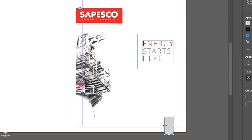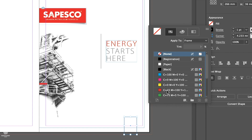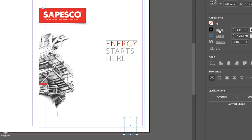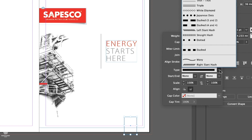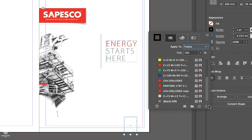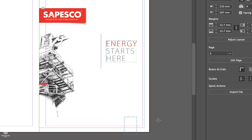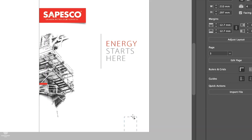We can hold Command or Control to increase its width a bit, and let's remove fill color, selecting none, and let's have a dashed gray stroke as well. So selecting our stroke type, dashed. There's nothing new here, as you can see guys, it's all coming from Illustrator or Photoshop. Let's select gray by clicking on that square, going to our black 60%, clicking outside so we can see how it looks. And let's hide our guides again, pressing W, and let's place some type in here.